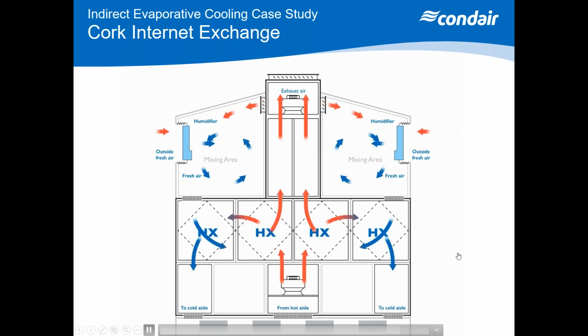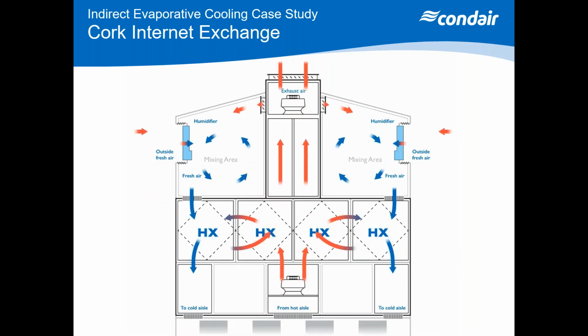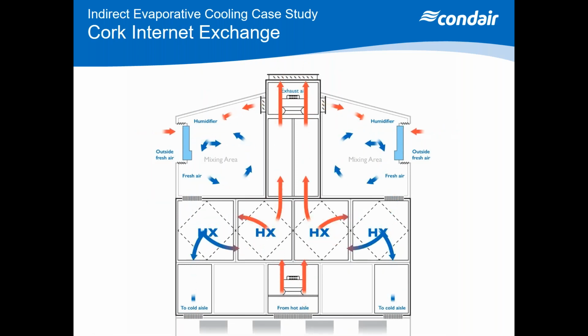So again, it's just like drawing the air from a space, having a cooling coil, putting the air over that cooling coil and putting it back in. But instead of the chilled water being your cooling medium, here we're using humidified, evaporatively cooled air.